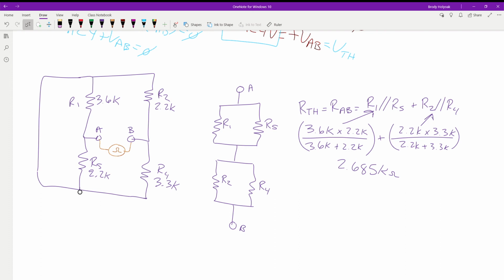That's what I'm saying. These ones are difficult for that fact, is we're using all the different tools that we have. We're using Kirchhoff's law. We're using our parallel laws. How many current paths do we have from one point to the other? That's what determines what's in series, what's in parallel. It takes some time. But this is the big key here, is being able to redraw your circuits like this. Make sure you have all the connections between each component.